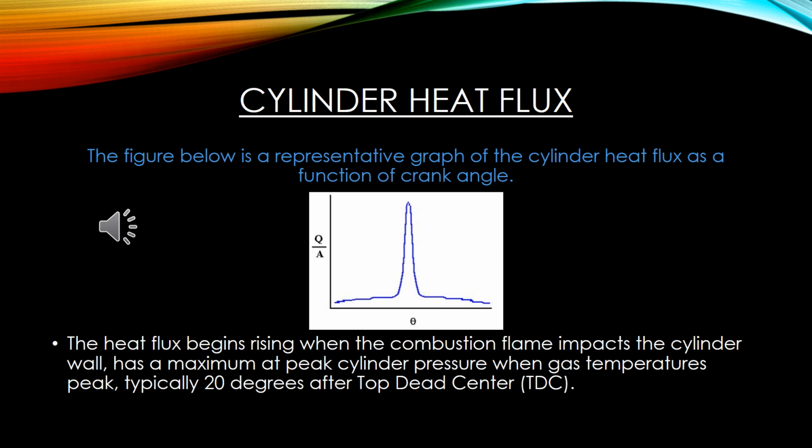Finally, cylinder heat flux. The figure below is a representative graph of the cylinder heat flux as a function of crank angle. The heat flux begins rising when the combustion flame impacts the cylinder wall, and has a maximum at peak cylinder pressure when gas temperature peaks, typically 20 degrees after top dead center.